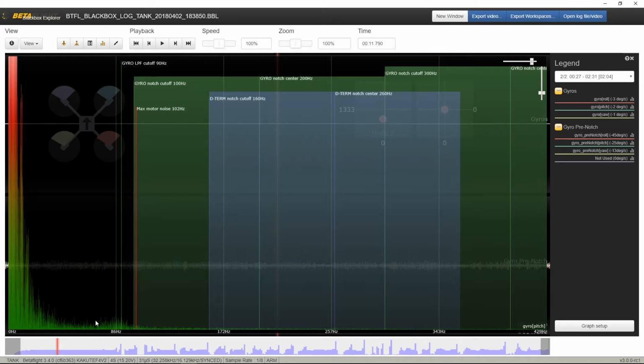It shouldn't be there. So we can lower the gyro low pass filter cutoff from 90 to 80 Hz. And this small peak gets a little bit more attenuated by the gyro low pass filter. This is our first guess. We set the values to the flight controller via the Betaflight Configurator. We will go fly. Again, some short line of sight flight with black box logging enabled.